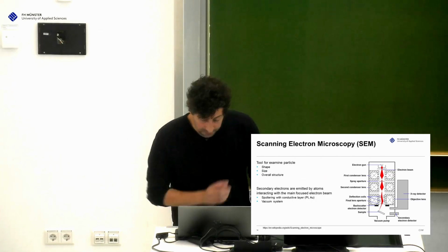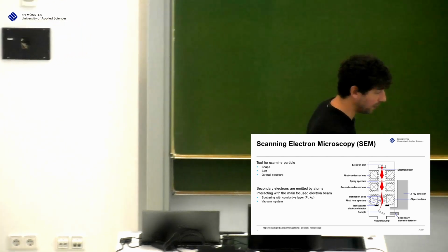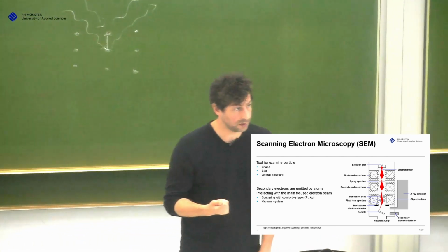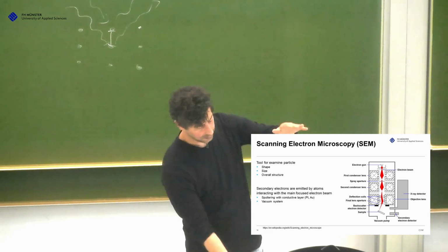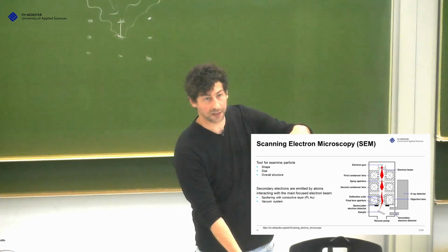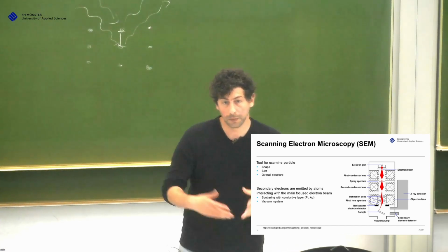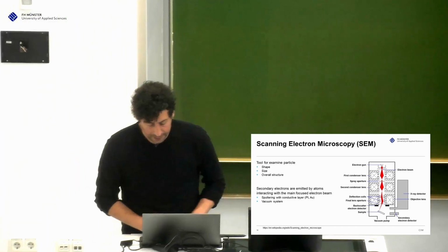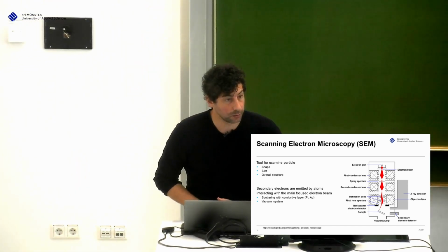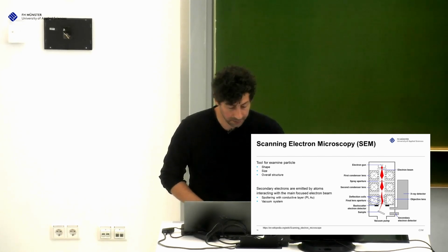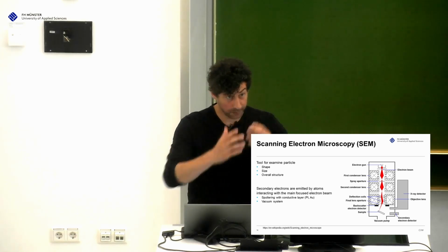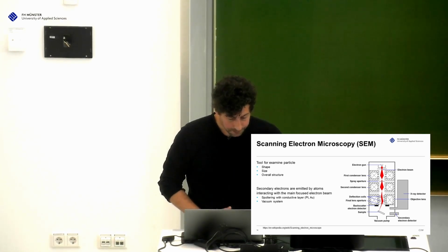So, this is a very useful tool and even more simple than a TEM and cheaper than a TEM. SEMs you can buy now, like in the past a computer, this size, you put it on a table, open it and put your sample. The vacuum is not always that high, but there are high vacuum systems which are going to 10 to the power minus 7. And what you can take a look at is shape, size, the structure, granular, basically all what you mentioned.